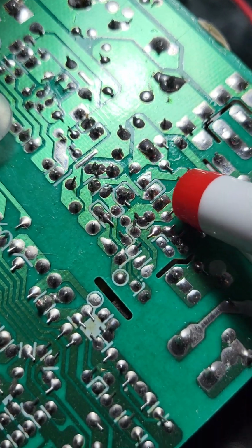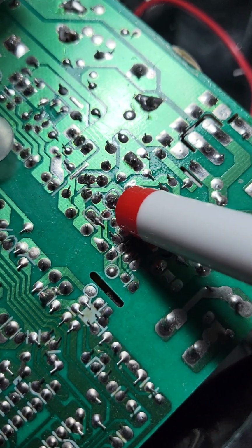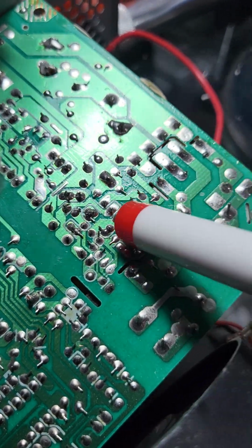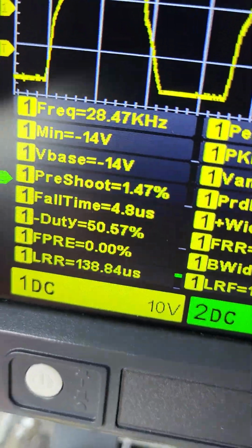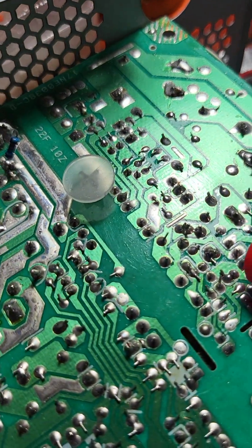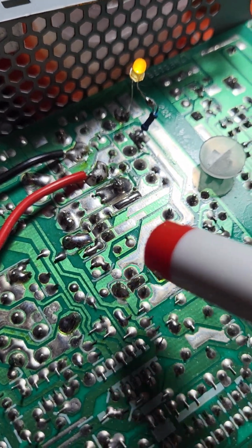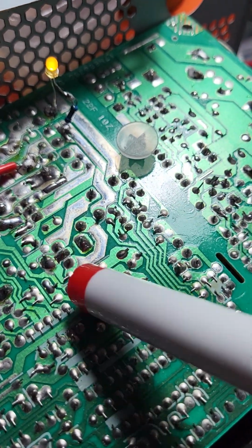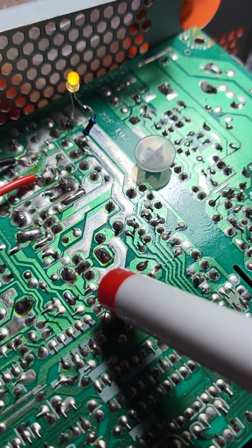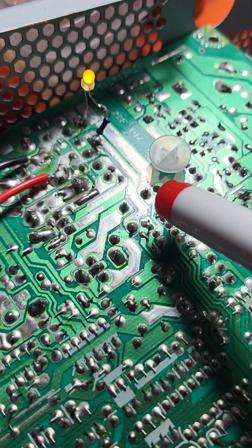The concept here is switching. Again, there is an oscillator in this portion that generates this frequency, 28 point something kilohertz. Then it switches the transformer to have an output here, and so whatever the frequency in the primary would also be the output of the secondary section, but at a lower voltage.